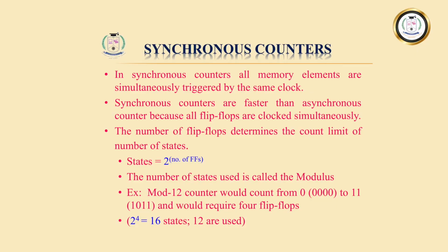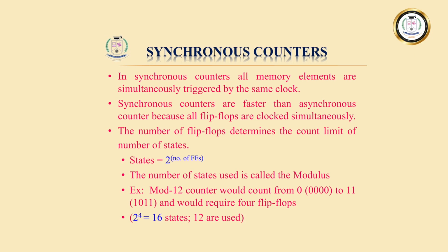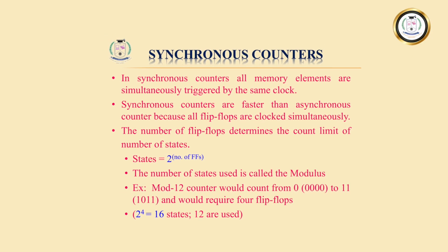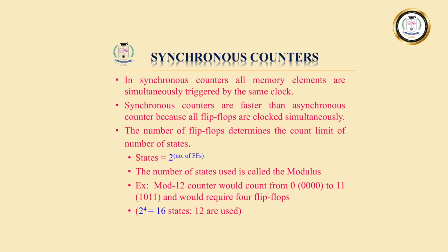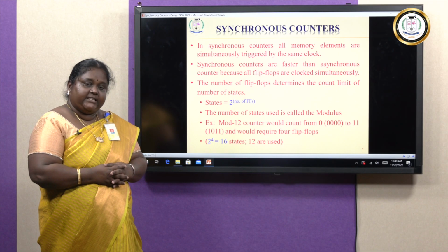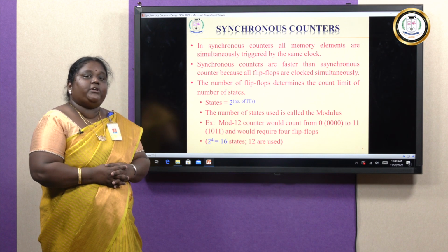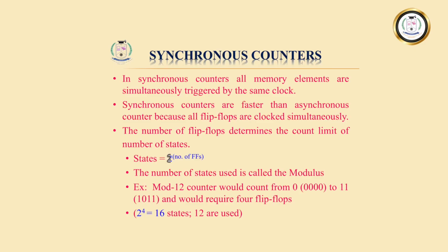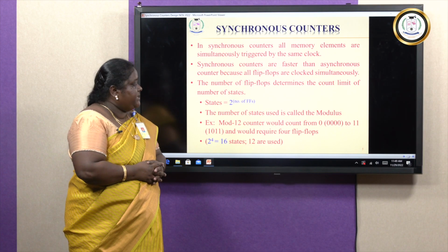Here the number of flip-flops determines the count limit, that is, the number of states the counter is going to have. For example, the number of states is decided by 2 to the power of the number of flip-flops. That is the design of the synchronous counter.